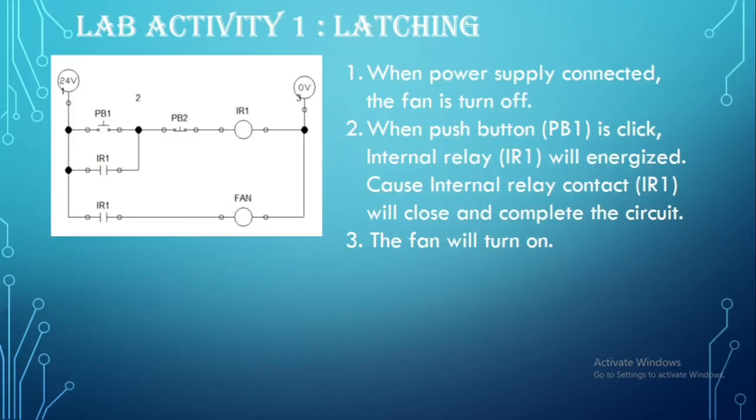Okay, for your information, for this lab activity we use Logo Soft Comfort software to run the ladder diagram. Look at the ladder diagram from lab activity 1, latching. When the power supply is connected, the fan is turned off. When push button PB1 is clicked, internal relay IR1 will energize, causing internal relay contact IR1 to close and complete the circuit. The fan will turn on.